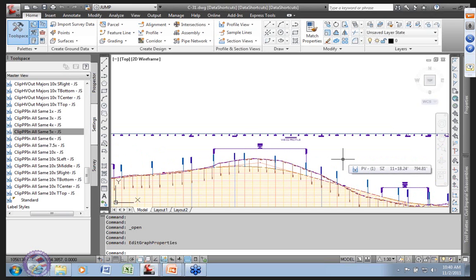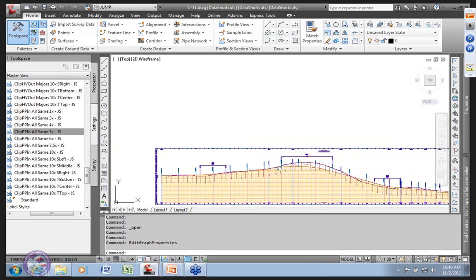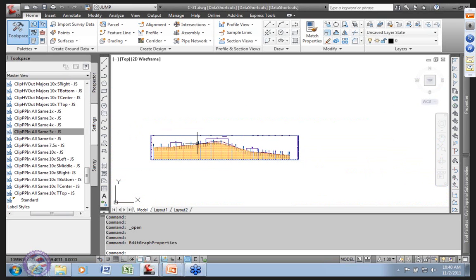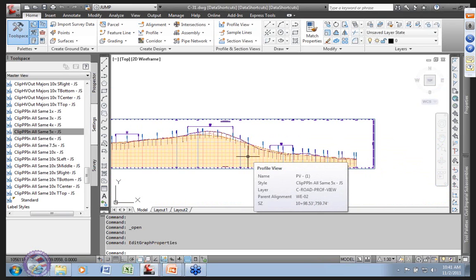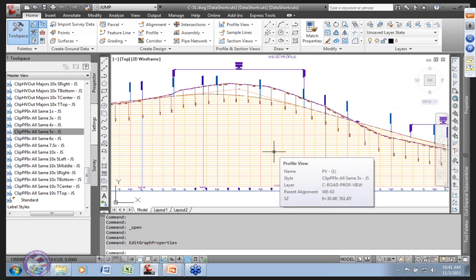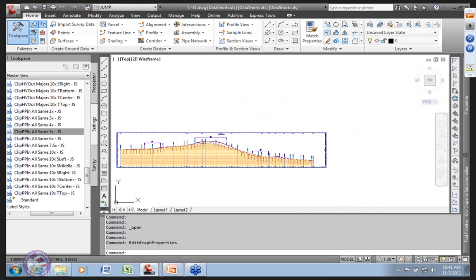Okay, so once again, everything else. Did I have to change everything else? No, I may have to rearrange things if I'm changing how the data is displayed. That may require that I make some modifications to other things, but this ability to have consistent styles with consistent names that are replaceable, that employ the same look and feel all over the place, is tremendously productive inside Civil 3D and gives you tremendous publication liberty with what you want.